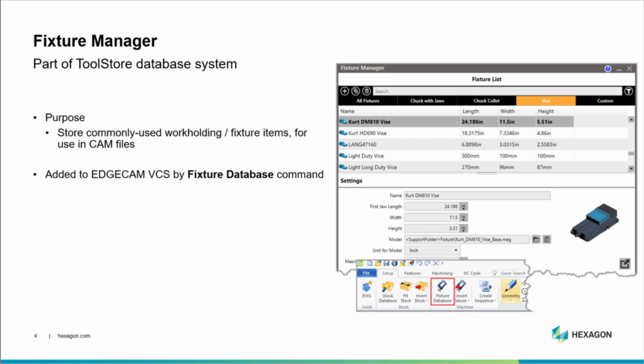But what about less complex machining setups? If the CAM user must create a 3D CAD assembly containing each item in the CAM setup, the process would be burdensome. For complex jigs and fixtures, there is often value in a 3D CAD assembly beyond simply preparing items for CAM. Because the upfront engineering work has a good payoff, users are willing to invest the additional time. But would we go through all that effort simply to add a vise or chuck to a setup? Probably not, unless it's very easy to create the machining assembly.